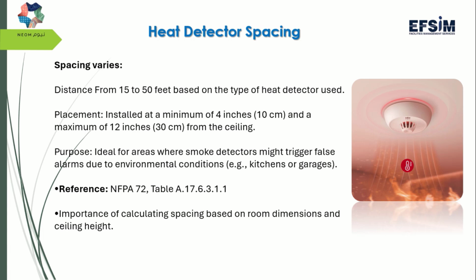I mean, too much heat, some kind of vapor, some kind of steam, like in open environments, kitchens, garages. If we install smoke detectors there, they might trigger false alarms all the time. So we need heat detectors in these spaces, premises, and locations.